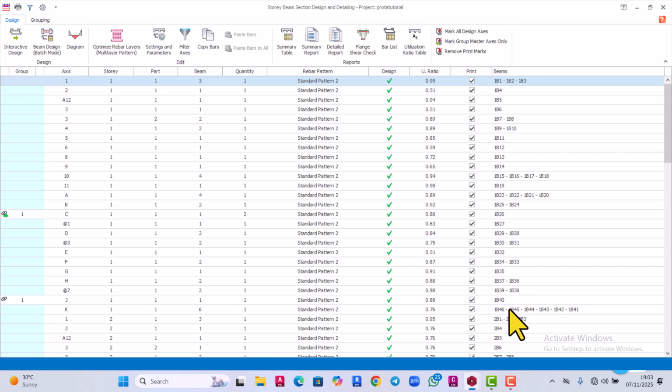So for this plain beam, it's normally at the ground floor level. One of the main purposes there is to tie the columns, and because of that, when they are constructing it on site, they will be resting those beams on the wall. It's not like the beam is entirely suspended like the first floors, the second floors or the roof beam.